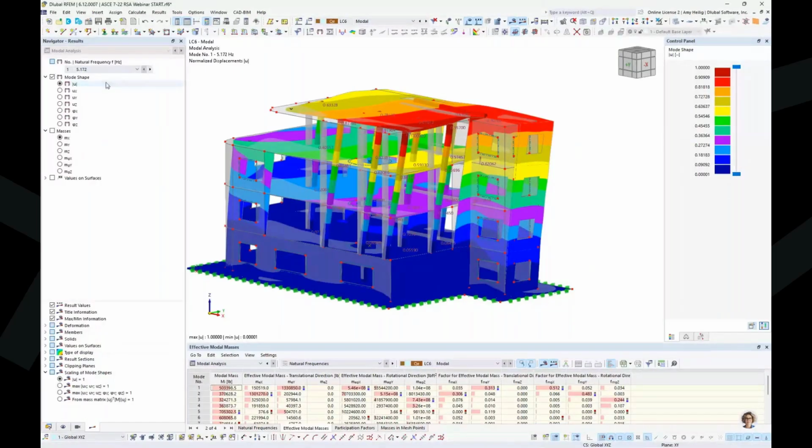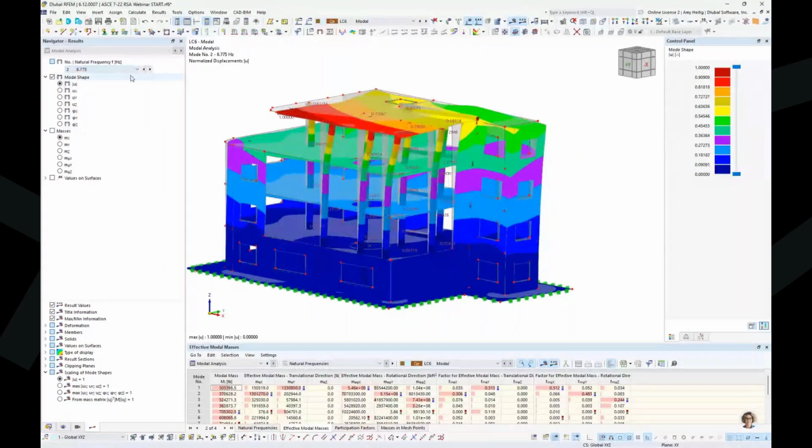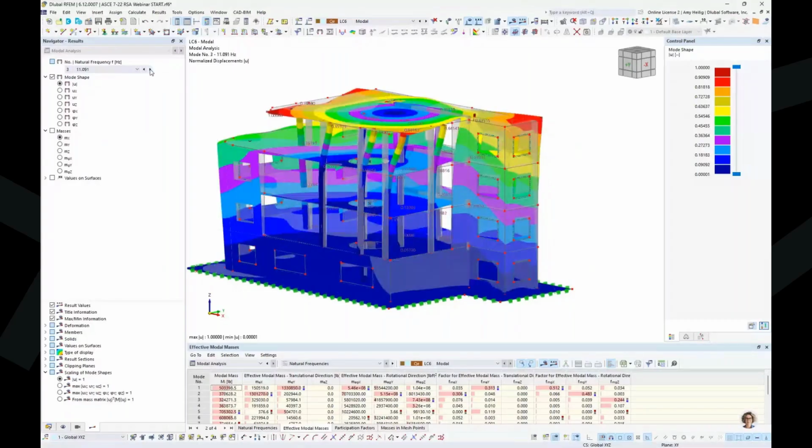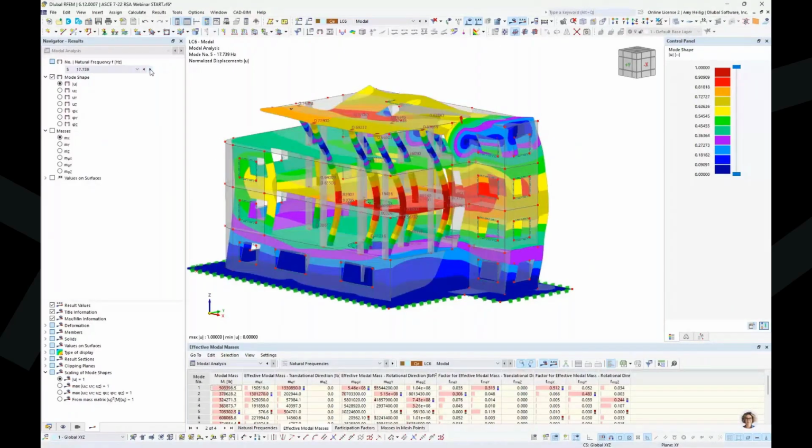Currently we're viewing the mode shape, and within this dropdown, we can take a look at the 10 different mode shapes that we have solved for, and we'll see the structure response adjust accordingly. The scaling of the mode shape is also set down at the very bottom of our navigator. By default, we scale them to a factor of 1.0, considering the translational directions, but you could make modifications to this if you see fit. Again, we probably won't. We'll typically leave this as the default scaling.